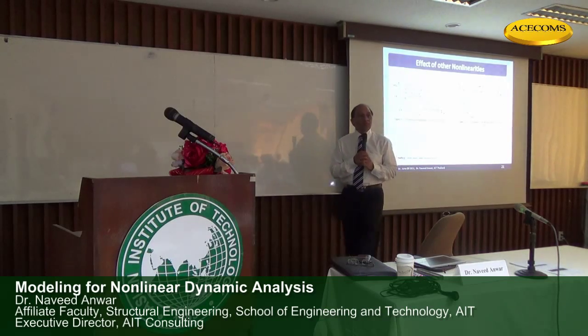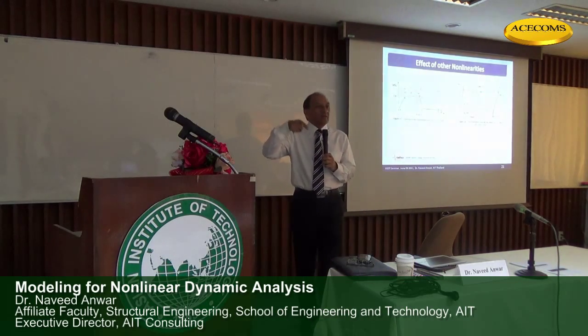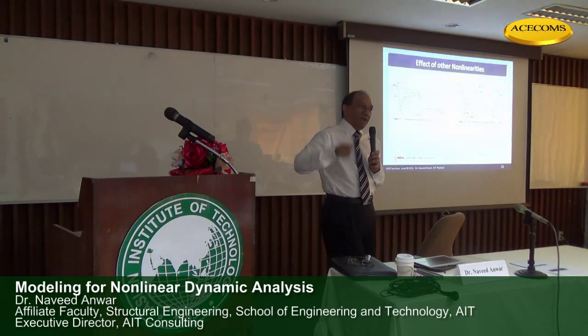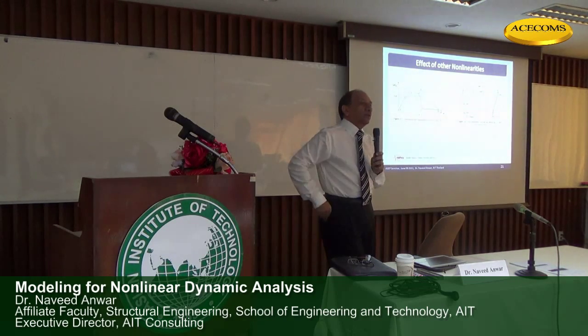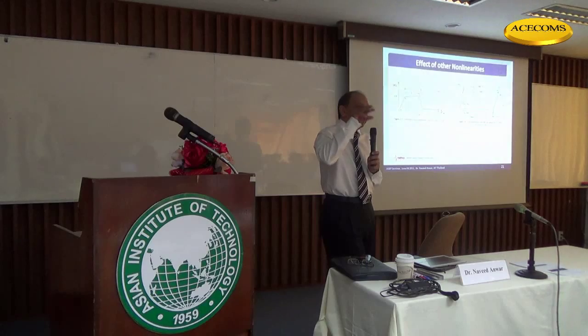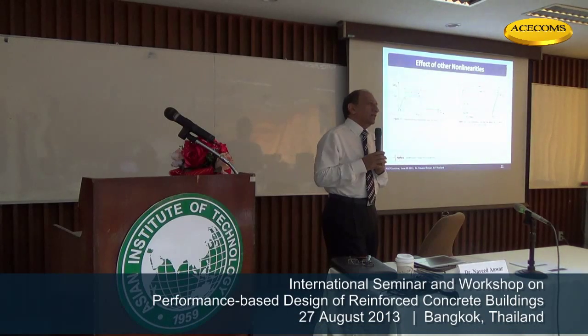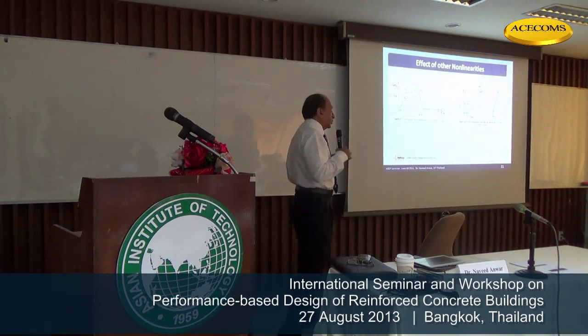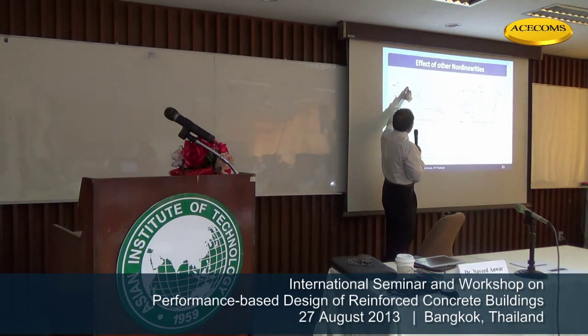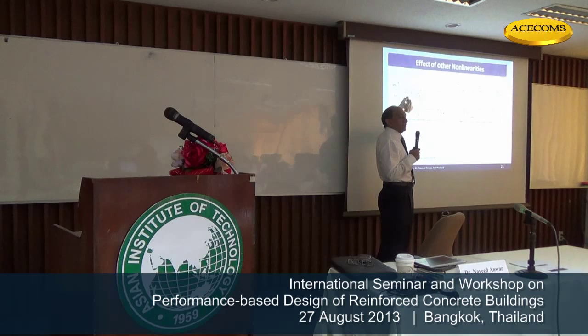And this helps us to define our nonlinear model input. This becomes our input. So every type of material response, cross-section response, can be converted into an equivalent ABCDE curve, and then we put this curve as an input to the program. And then after you put that input into the program, it does not use that elastic curve anymore.